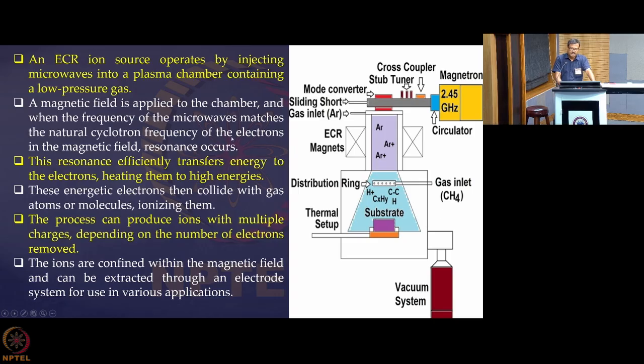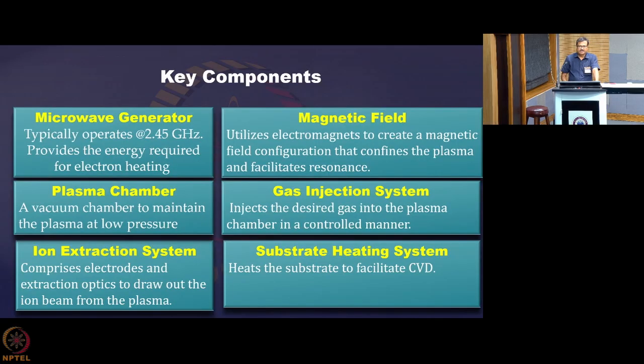continuous manner. You remember that some gas you are injecting through here, some gas you are injecting through here, and the pumping system should be such that it can maintain the pressure inside the chamber in a very stable manner. So you have to control the sucking system in a way that the pressure that you have created inside the chamber is maintained without time variation.